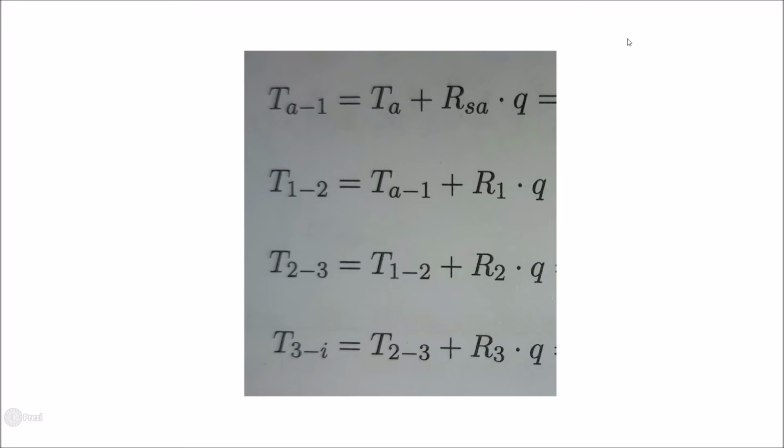As a last step, we now show the exact heat transition between the inside and outside of the wall. We do that, for example, to determine the exact spot at which the temperature reaches 0 degrees, or to see where we have a critical point with dampness. You start at the layer transition outside and always add to the current temperature from the point before the multiplied R and Q. If you calculate it through to the end, the current temperature inside should come out.